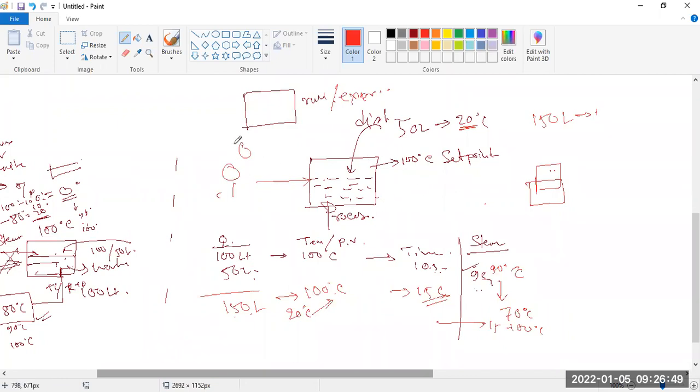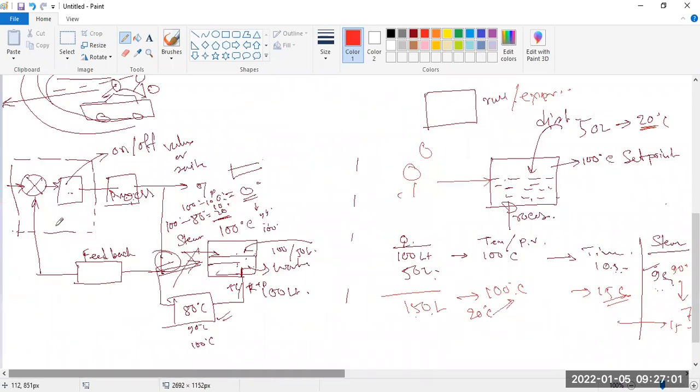By applying this, we are not applying many hi-fi technologies, because only a rule-based, normal technician can apply this. But in this case, this process control is a closed loop process control. Here there is a microcontroller-based controller and a sensor. If there is a problem with the sensor, say the temperature is 100 degree centigrade but your sensor measures 90 degree centigrade, your process never gets the process value accurately. But here only your experience is working.